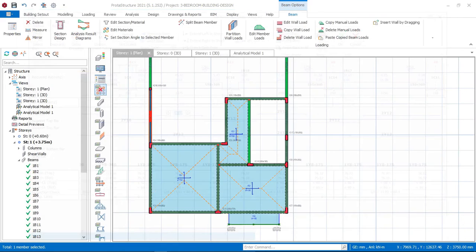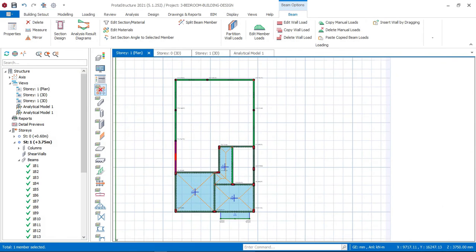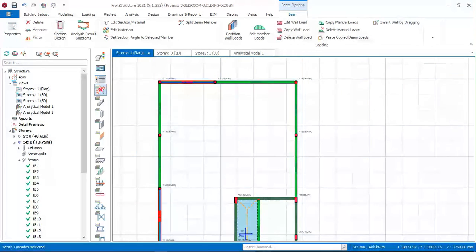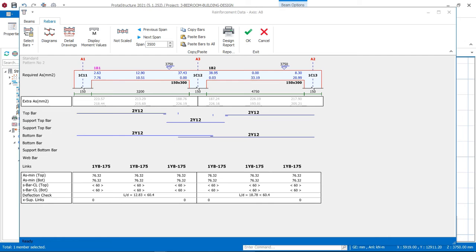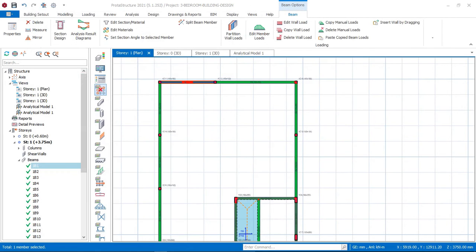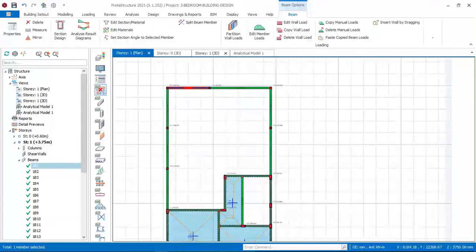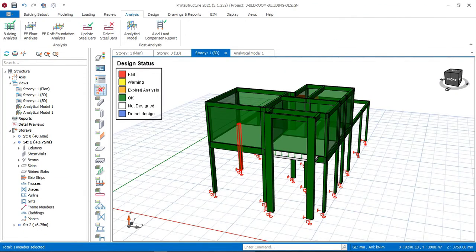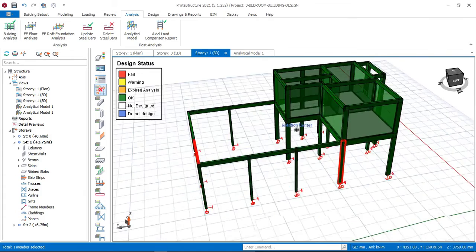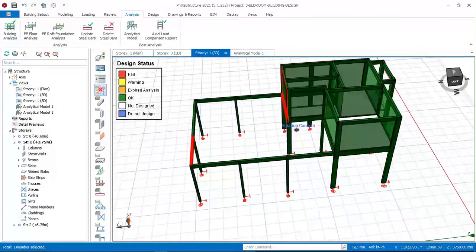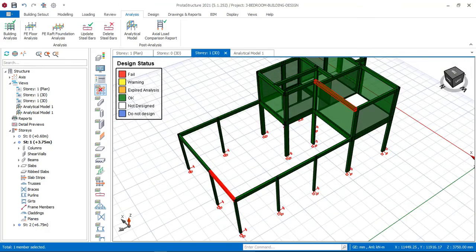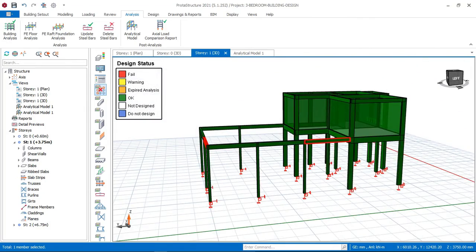So I'll click on OK, and then we will have to check this also. I'll show you the reason why I say that place is not carrying slab. So this place right now does not have any slab, so all this place becomes 12. That's okay. Now if we check on our 3D view right now, let me just show you why I say that place is not carrying slab. You can see how the building is. This place is the place carrying slab. If I go out from this particular view, you can see that this place is carrying slab, while this place is not carrying slab. So that's how it is.